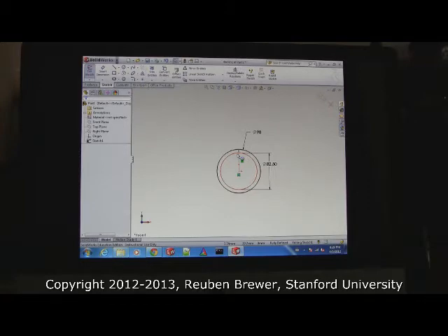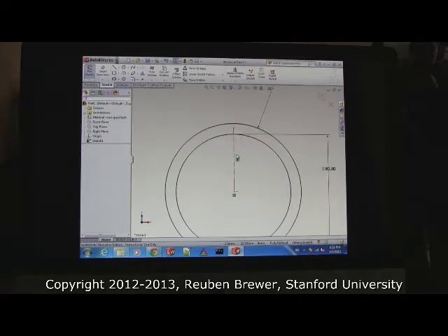So, one of the problems that you're having is basically if you're too zoomed out, it snaps to things kind of randomly. If you want it to snap exactly where you want it, you have to zoom in so that basically your mouse is only over where you want it to snap. So, does everyone have something that looks like mine? Okay. Now take another circle and center it at the top of that line.